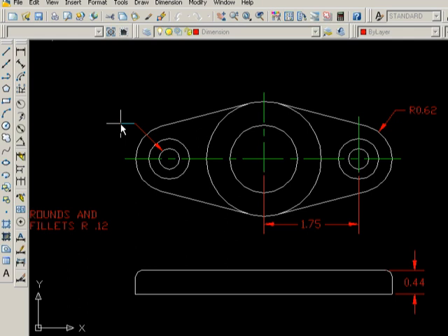You notice I have symbols in there. That theta symbol is a symbol for diameter, and also the U shape is a symbol for what's called a counterbore. All right, I'm going to go ahead and type in the text first and worry about those later. So I'm going to type in 0.38 in my command line. I'm going to press enter. Now my command line reads enter next line of annotation text, and I'm going to type in 0.75. I'm going to type in actually CBOR 0.75.